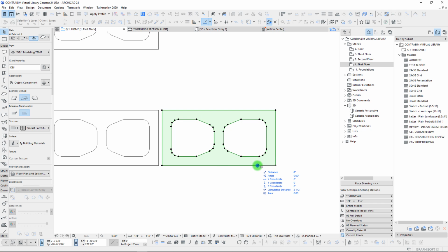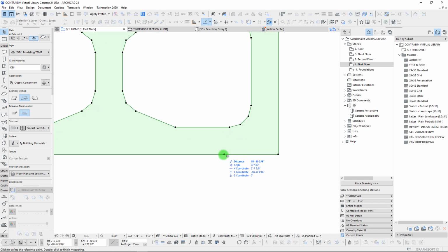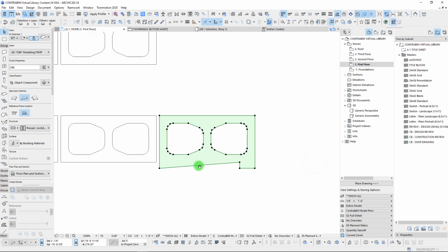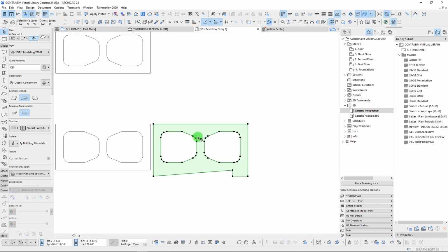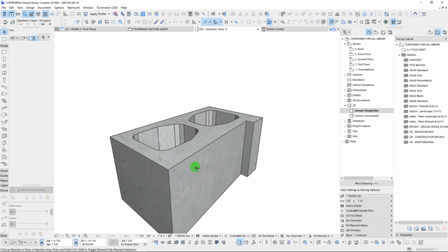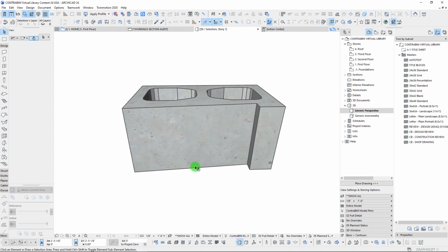And then from here, we're going to give it a point. And I'm just going to double check there to make sure that that's exactly what I wanted. So yes, it is. And all right, so from here, let's bump this out 1 inch. And then we're simply going to extend this one to meet it. And okay, so there we go. That would be a quick modification to create that type of spade block that we're just looking at.